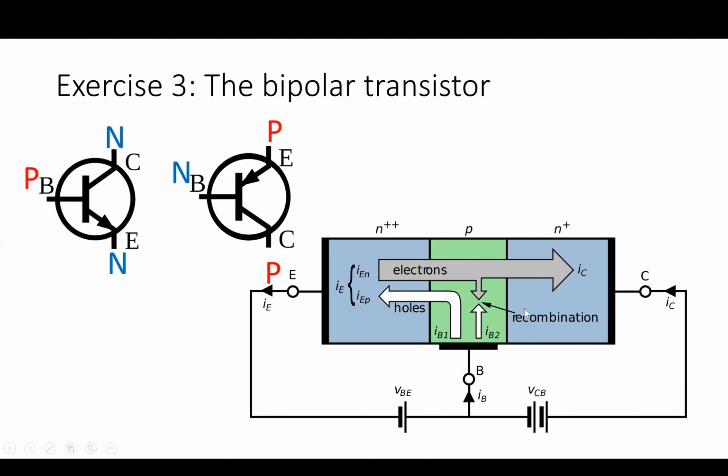But, oh, wait a minute, I've got that wrong. Okay. Let's have a look. This is the P side, this is the N side. And so if we make this positive, that's right, current is going to flow around this way. So this looks like the anode of the diode. This now is another piece of N-type silicon wedged up against this P-type silicon. So this now, if this is made positive, is reverse biased, opposite bias to this diode here. And so no current at all can flow here.